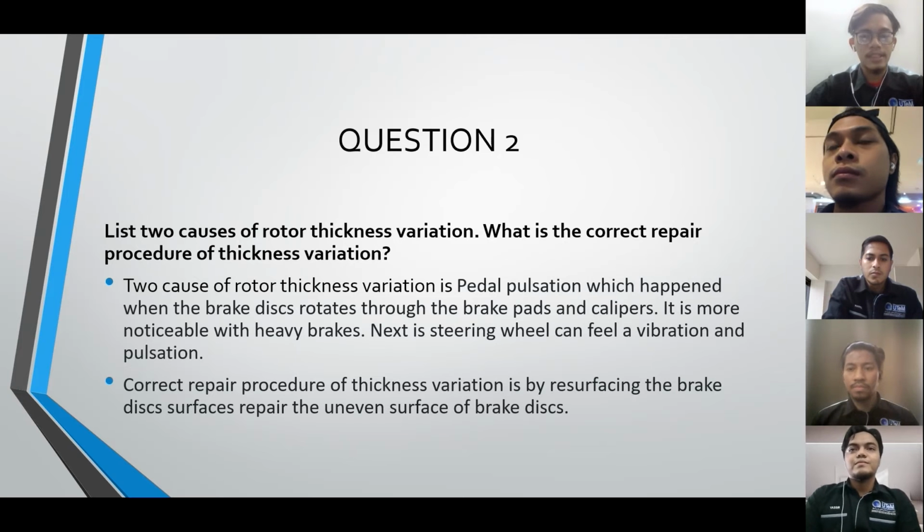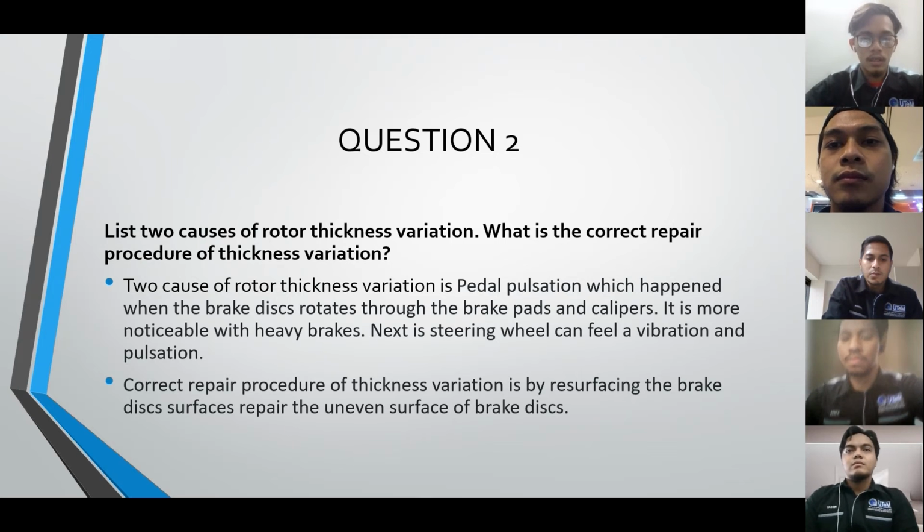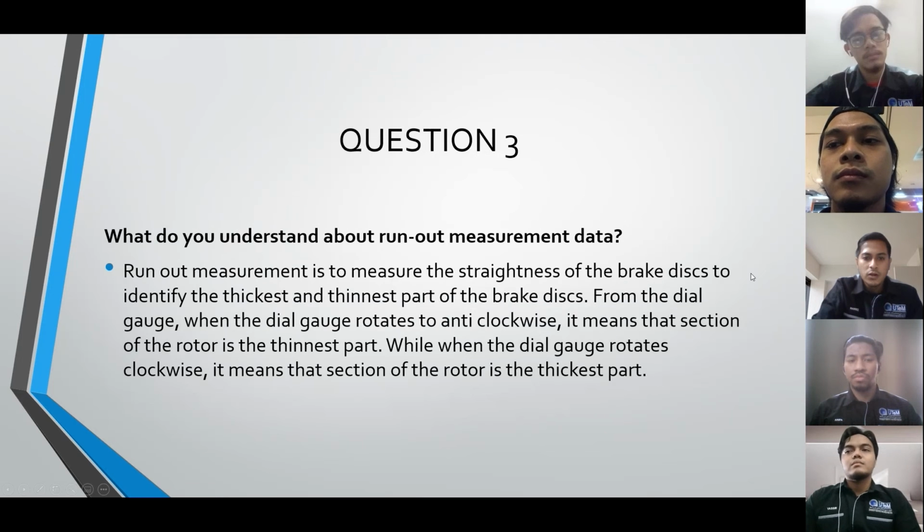Next, the steering wheel can feel a vibration and pulsation while you are driving. So the correct repair procedure for thickness variation is resurfacing the brake disc, which repairs the uneven surface of the brake disc.